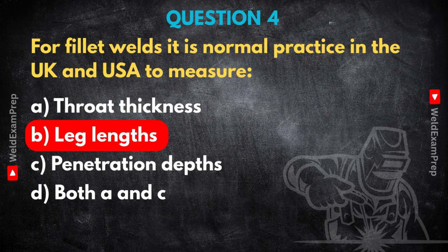That's a very astute observation. It's a fundamental aspect of how welding design and inspection work together. Engineers absolutely design based on the required effective throat thickness. That's non-negotiable for load capacity. However, they build the practicality of measurement into the system. Design codes and standards provide relationships, formulas, or tables that link a minimum required leg length to achieve a certain effective throat thickness. So there's a known correlation. Precisely. These relationships usually assume a certain minimum root penetration and a flat or slightly convex weld face profile.